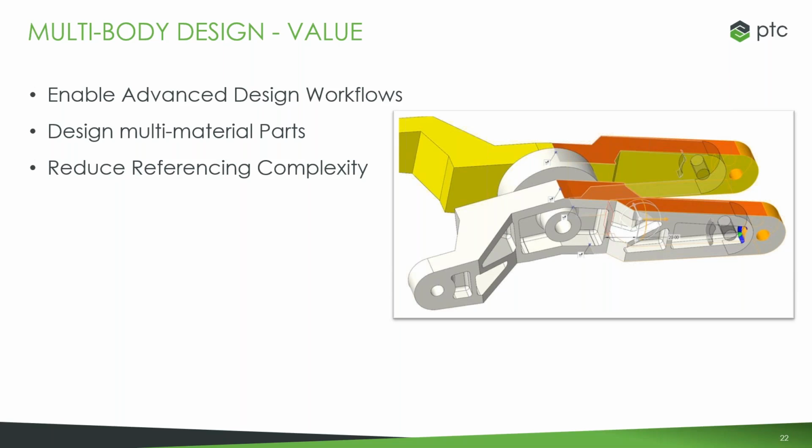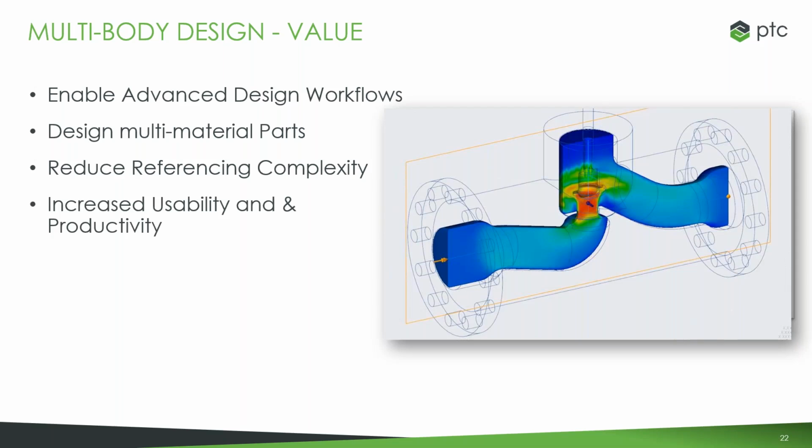Reduce the design and data management complexity by avoiding external or circular references inside the master model, and improve the flexibility in geometry visualization. Reduce the need to switch between solid and surface modeling, creating designs faster using body booleans and split. Easier data exchange of multi-body parts from and to other CAD systems.